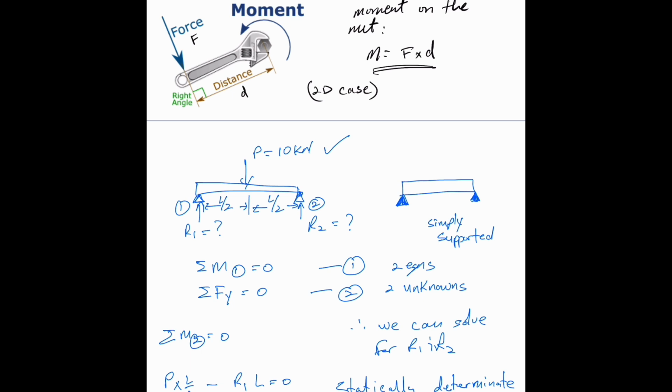So the beam is allowed to rotate on that end. If you were to draw the deflection of it, let's just exaggerate the deflection. You'll notice now that the point remains the same, but the beam has now rotated about that point on the end. The beam started off here, now it rotated up in a way. So there's zero reaction moment, meaning there's nothing holding or preventing the end of the beam from rotating. So it's free to rotate. That's what we call simply supported because it's just resting there.